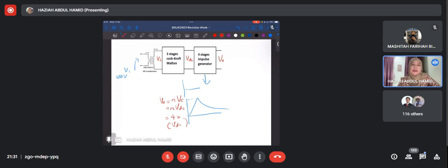It looks difficult but actually it's easy. So don't think it's too complicated. Once you get the labels, sketch and make sure you show all the formulas and all the steps you used to calculate the input and output voltage. Make sure here you label the input given, here show how you get V2, and then sketch the input and the output here. And then move to the second stage, Cockcroft-Walton.